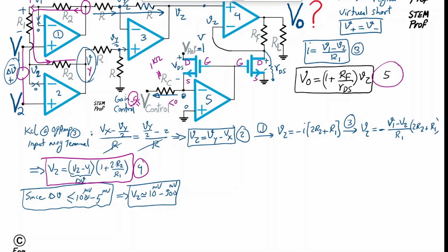As we reduce V control from 0 to the most negative value, -5, we are increasing the current here, and the current is simply this current. Let's say it is the drain-source current, because this current can only come from the drain source; it cannot come from the input terminal of the op-amp, which has infinite impedance.